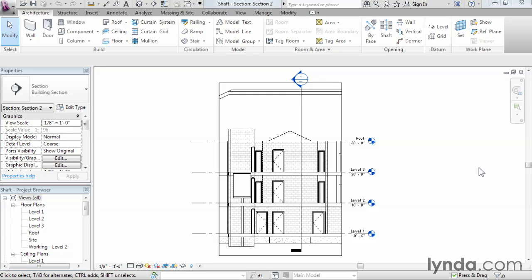In some cases, you will find it easiest to edit the sketch of the element in question to represent such penetration. This approach would work well for floors, which represent double volume spaces, for example. In other cases, you might use an opening object to actually cut through the solid geometry. So in this movie, we're going to explore a few examples of opening objects, and I'm going to start with a shaft opening, and the file I have open here on screen is called shaft.